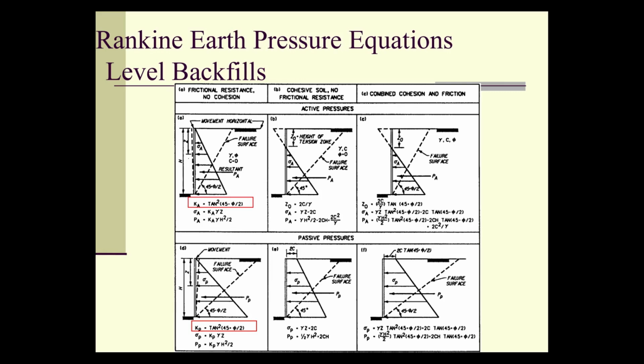If you recall from lower and upper bound theory, if we dig down and excavate in a cohesive soil, we're going to get up to a certain height where you are able to have a vertical cut. Well, if you were to put a retaining wall in a purely cohesive soil, and there are good reasons not to do this, by the way, sometimes you're forced to, in which case you have to make provisions for the drainage, and we'll talk about that later.